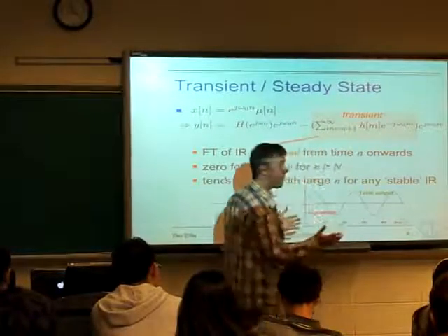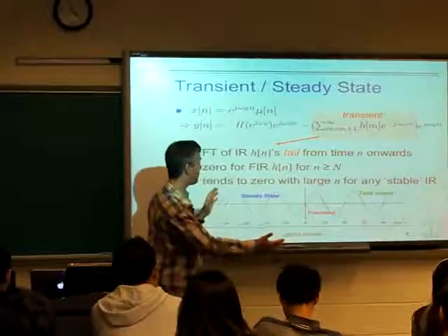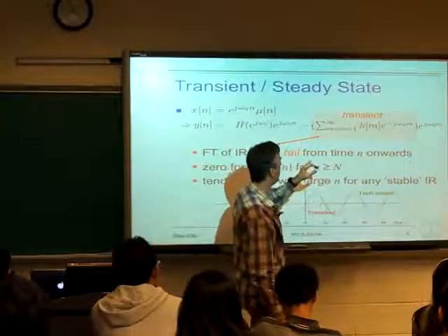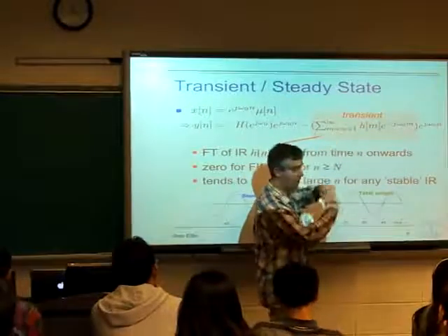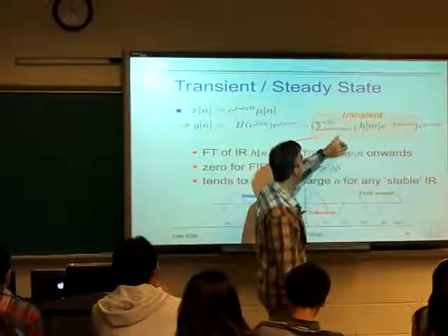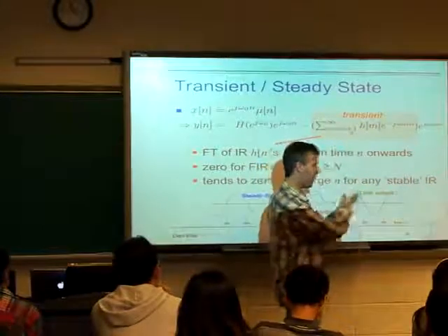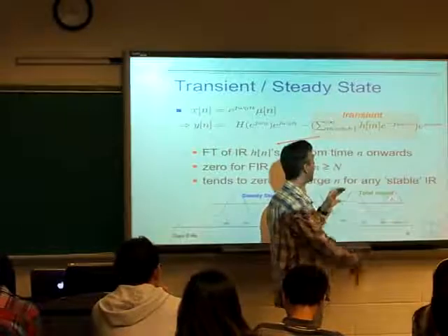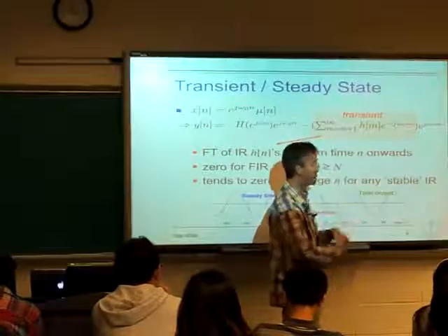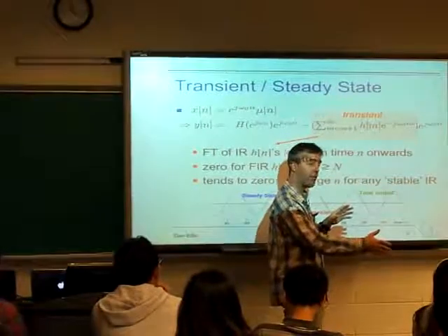So if we have an impulse response that's got some set of points, if we started from 0, we just have the regular Fourier transform. But if we start from some larger value, it's like we've chopped off, we've zeroed out the first n values of that impulse response, and we're just taking the Fourier transform with the remainder.